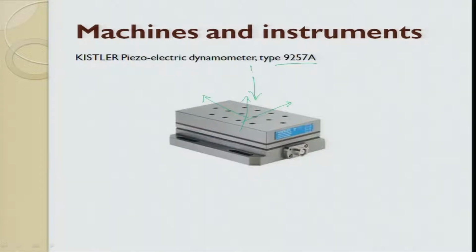This is the normal force, which we call Fn in case of grinding, and in this direction, this is Fy, or in these terms I will call it Ft. This is the tangential force and this is the normal force, right. And normal force is always greater than tangential force. This mechanical people know, right. I put it, this is Ft. Please don't get confused here.